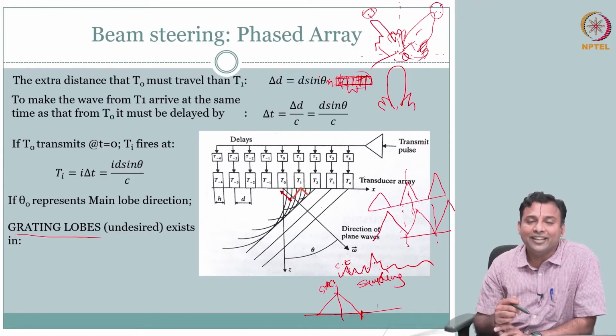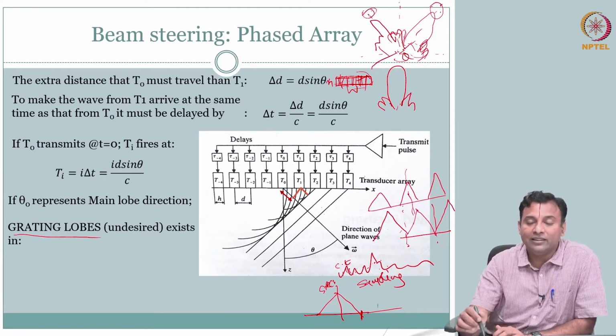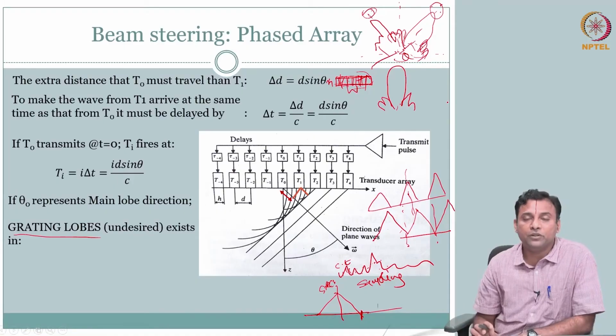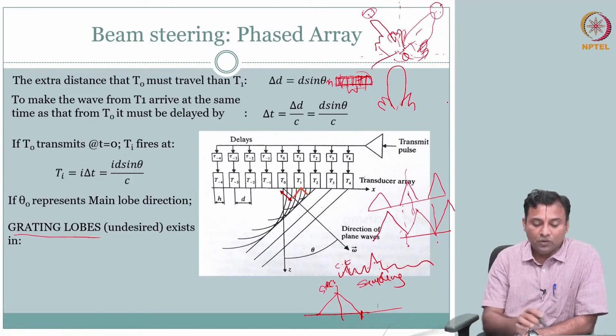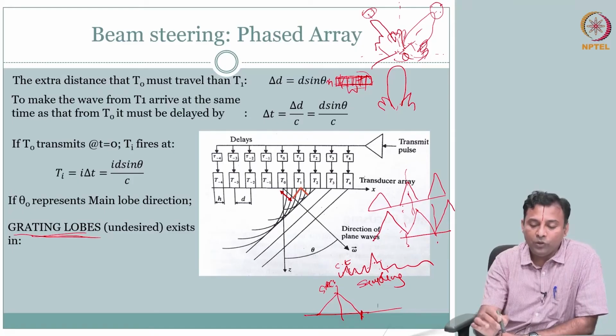Copies, right. If I sample very well, that is greater than your Nyquist, I should have these not overlap. I should have multiple copies, but the other copies should be small. So in order to avoid this grating lobe, there is going to be a constraint on how well you sample.